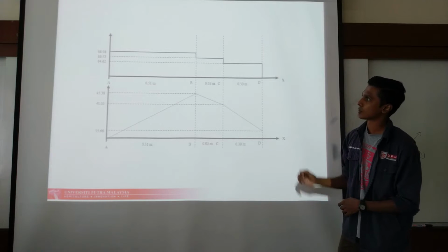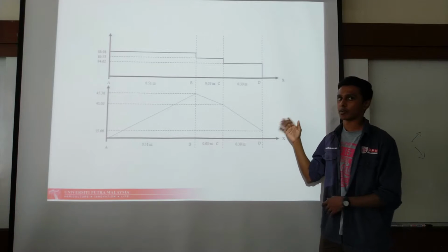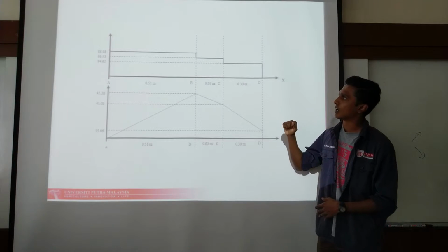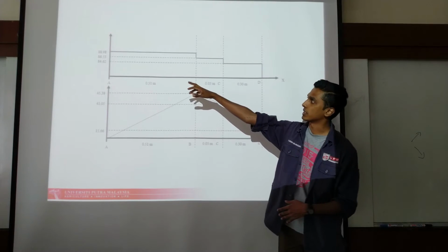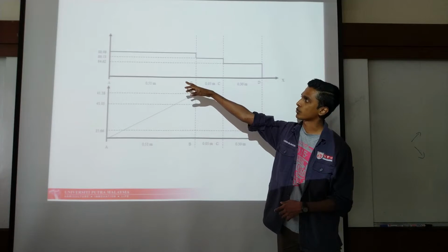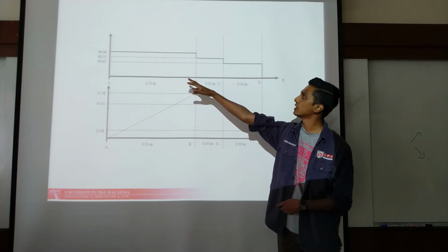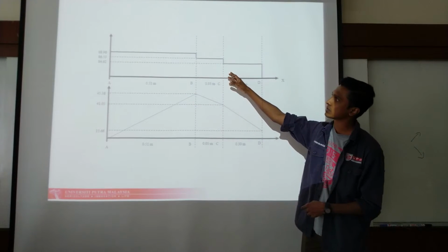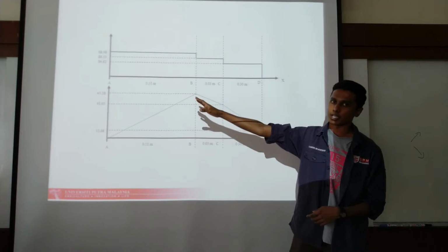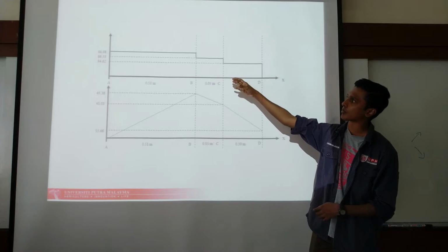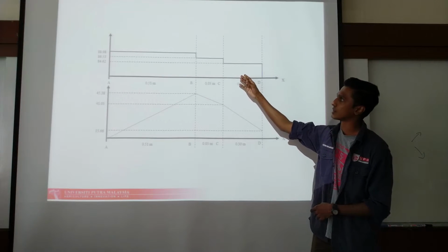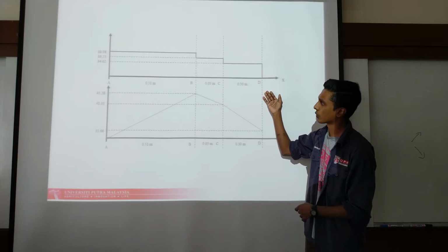Next, this will be the diagram that I've plotted. First, we can see that the highest force will be about 88.98 Newton, and it drops down as we proceed from A to D. It drops to 86.53, then 84.62. Next we'll go to 0.